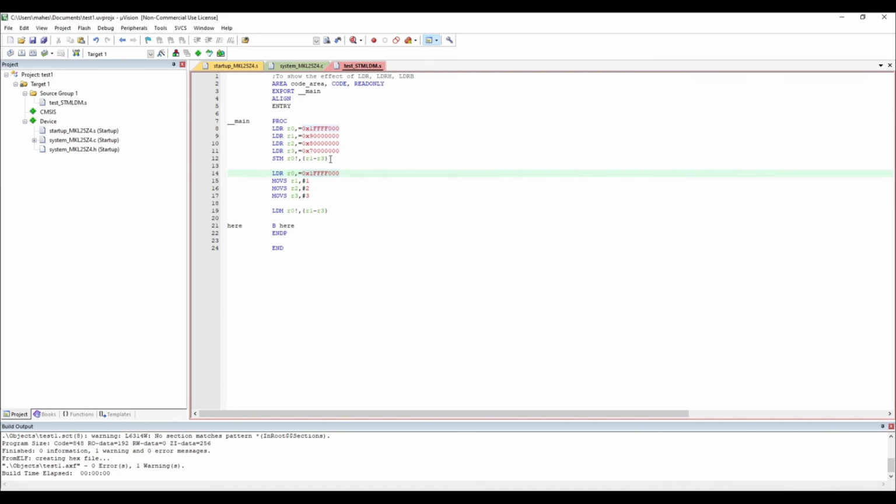Always remember, each location stores only 8 bits. So you will see that the R0 value will get incremented to C. Basically, you increment for 1 register, it's 4 locations. You increment for 2 registers, it's 8 locations. You increment for 3 registers, it's 12 locations, and 12 is nothing but C, right? ABC. Okay, so that's the thing.